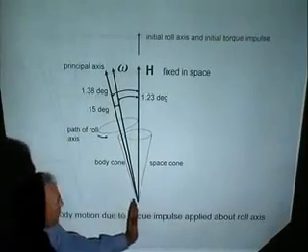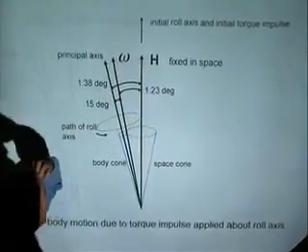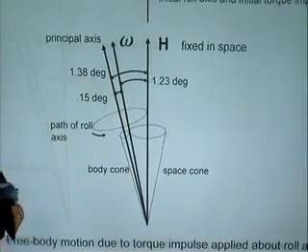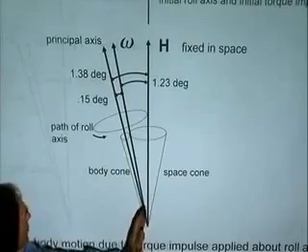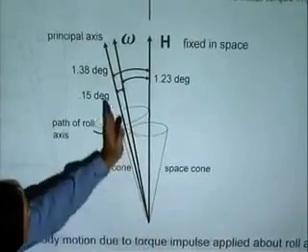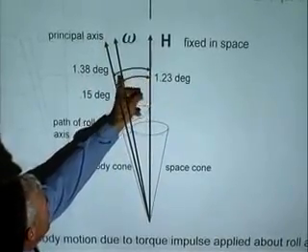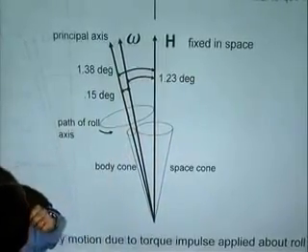The one where we applied a pure torque and got the angular momentum vector aligned along the desired axis for the barbecue mode and then turned the jets off, gave rise to an initial angular velocity that was not too far away, less than 2 degrees away from the initial angular momentum vector.